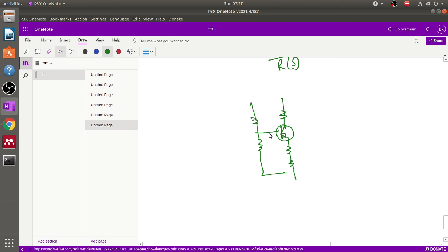Now realize this control system block by a circuit with these RC, these R1, R2. This is the input coupling capacitor Ci, and this is an output coupling capacitor C0, and from here we get the voltage V0. Here this is the bootstrap parameter, this small RE.